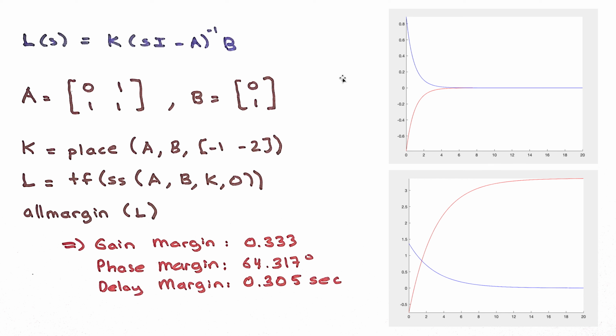All right, so I would like to illustrate just the gain margin. Basically, nominally, when I simulate x dot equals Ax plus Bu subject to the control signal u equals minus Kx, system states x1 and x2 go to 0 as t goes to infinity. This denotes the time. Once again, blue is x1, red is x2, since we have two states.